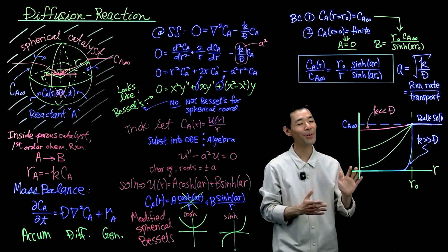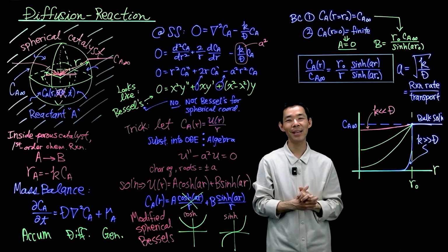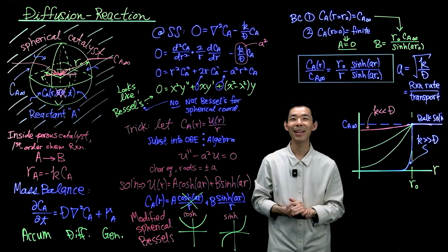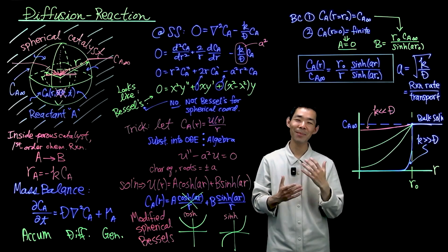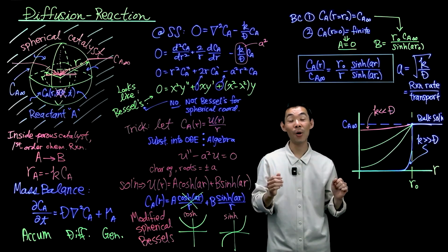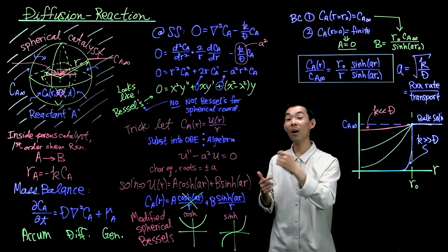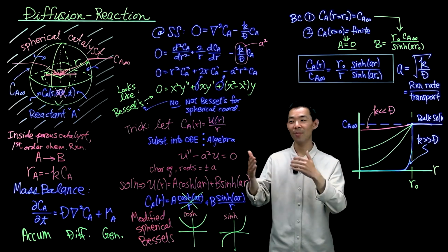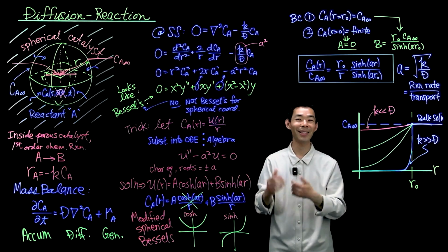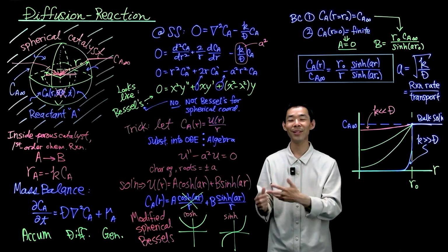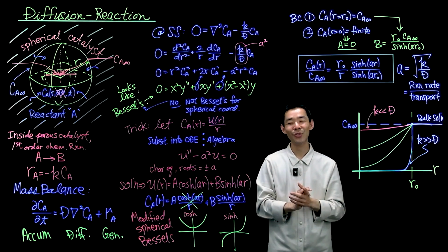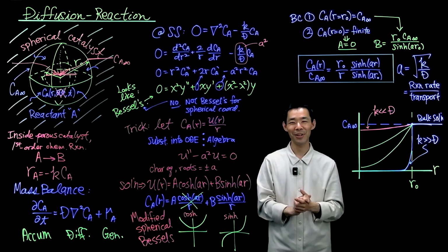And it turns out to give you a lot of really, really useful insights, in particular about the concept of scaling. And scaling is one of the most important subjects in my mind with engineering. If you make the reactor twice as big, what happens to your output? When you make the polymer molecular weight go from 10 to 100, what happens to your dynamics, the viscosity, the rate of reaction, the brittleness, ductility? This scaling concept is an extremely powerful tool that we use as an engineer.